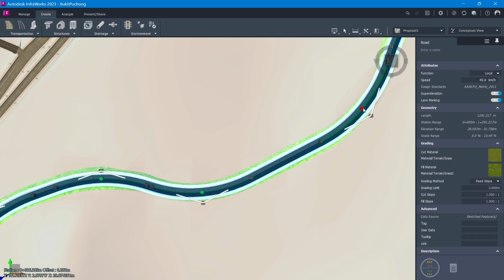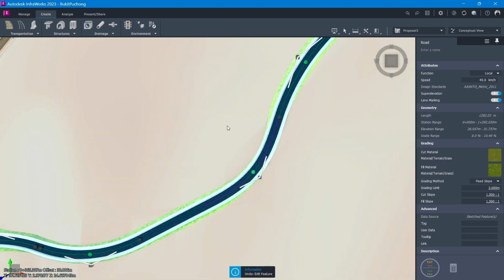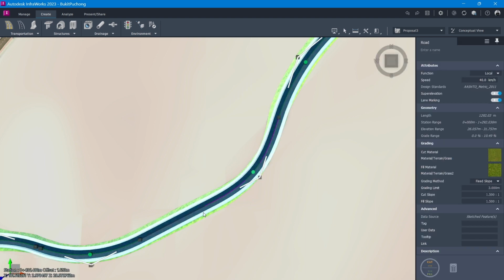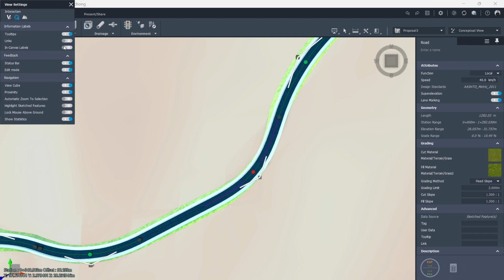And also you can change the geometry of the curve. I convert the geometry to a spiral curve, like that. The spiral is the transition from the tangent straight line before it reaches the circle or the curve. And then when you click here, because we closed the level, let me change it to make it canvas level. So then you have the geometry of this one.